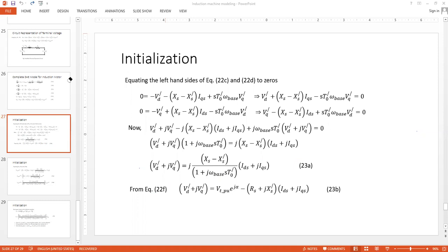So in summary, what we have covered, if we start from the beginning, we covered the synchronous generator modeling. In the synchronous machine part, we covered the synchronous generator in detail. Then we came up with the exciter model. Then we saw that, with the introduction of the exciter, we have some stability issue. So we tried to design the PSS. And we found that with the proper designing of PSS, we can get rid of the problem that gets introduced with the exciter, the high gain exciter specifically. So this was one break there.